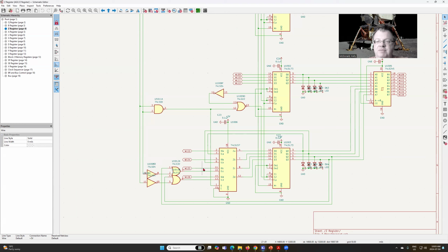So normally this selection signal here we're going to generate from basically a NAND of the two control signals. So if we don't have either asserted, we're just going to select option A, and that'll just load the bus data in normally.